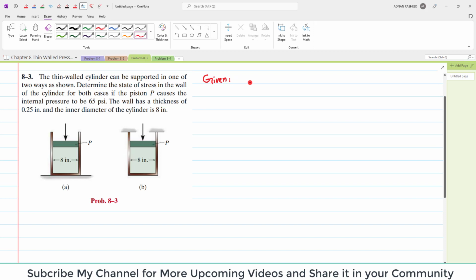So in the given data, it is given that this is a thin walled cylinder, and the internal pressure P is given as 65 psi. The thickness of the wall is equal to 0.25 inch, and the inner diameter, di, is equal to 8 inch. So from the inner diameter we can get the inner radius if we divide 8 by 2. So 8 by 2 is equal to 4 inch.